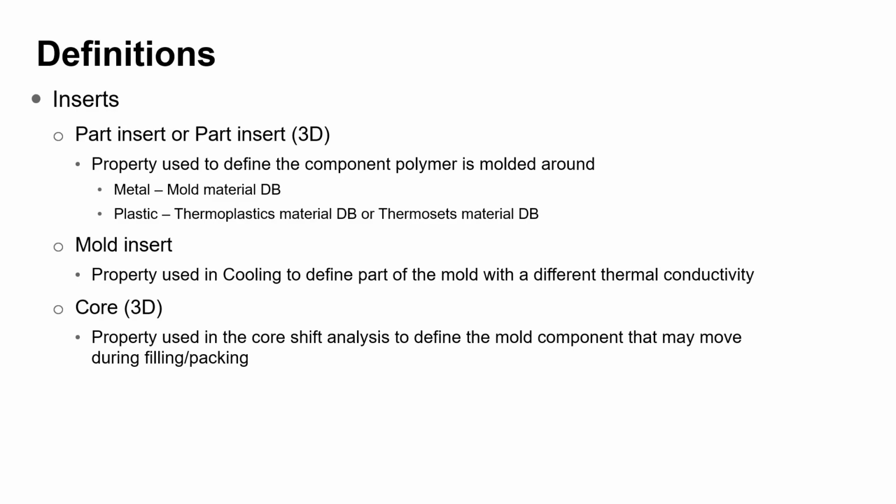Particularly, what happens in the insert, if it is plastic, then it resists the heat differentiation. It acts as a resistance to it. And if you are using copper or aluminum, which would have a little higher thermal conductivity compared to the default P20 steel that has been used, it plays a very crucial role.